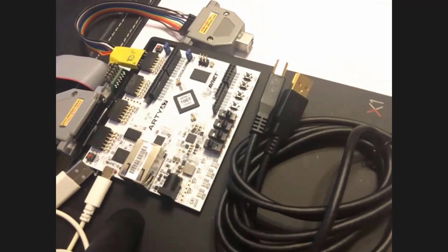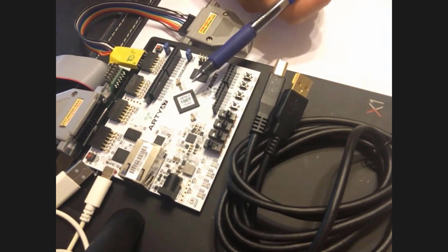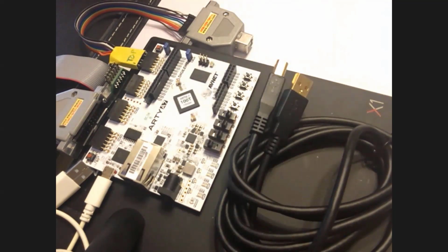Okay, before we can load and run the executable that we just compiled, you will need the following to connect to your host machine. The first being an Arty A7 board, which is made by Digilent and available from DigiKey, as shown here. I would recommend you grab the 100T type one, as it has a larger FPGA footprint. You will also need two types of USB cable. The first being a type A to a micro B, where the micro B is connected here. This is for powering the board as well as providing console output.